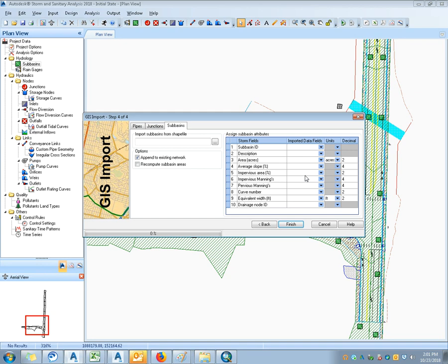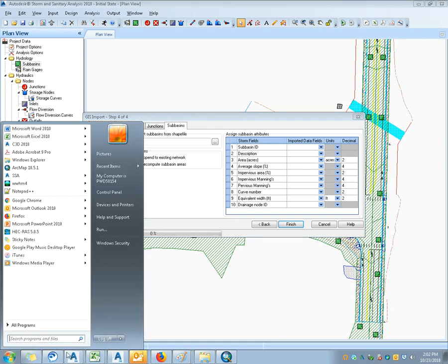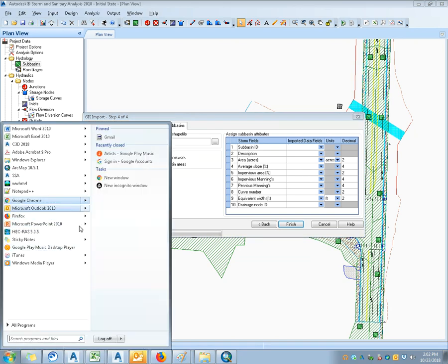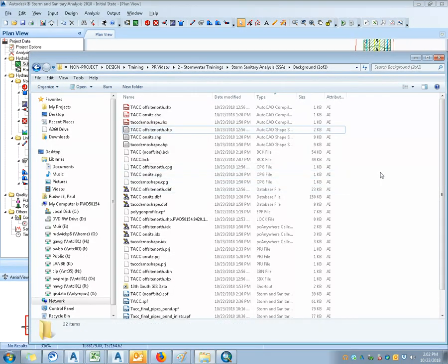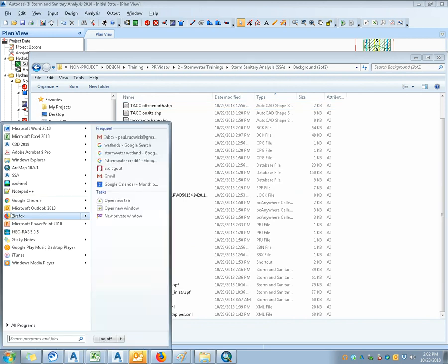So what I had always done as a workflow was go into the GIS and say I had a subdivision. I would call it all impervious, say, and just blanket it with one polygon. Then trace over the stuff pretty quickly in the aerial and cut out for existing condition, and then just give it a value in the database table.